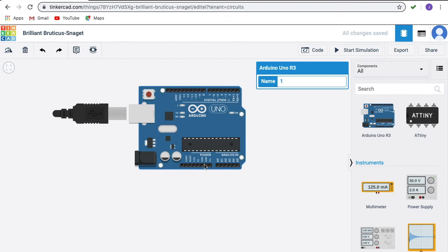The first set is about power supply, the second set is about analog inputs, and the third and fourth are about general purpose IOs or GPIOs, which can be used as digital input output or PWM output, or some specific application might be there for those signals. For those purposes we can use the third and fourth sets of connectors.